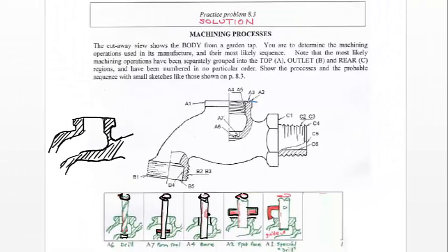Next we will be doing part A1, and this part will be a special drill. Due to the tap shape being irregular, it cannot be clamped normally like you would a cylindrical piece and then do a lathe process around it. So what we're going to have is actually a special drill with a guide in the middle and this cutting tool jutting out of it. When the guide is rotated on its axis, the cutting tool will go around in a circular motion and cut out the material until we get the radius needed for A1.